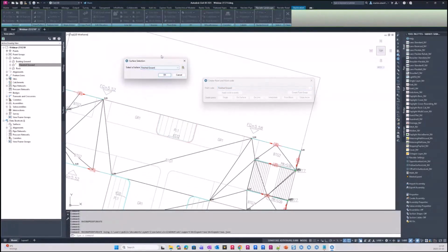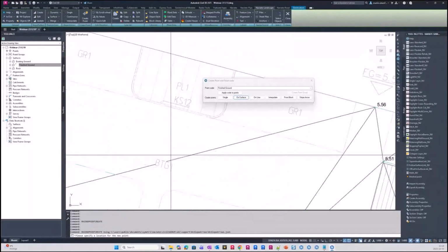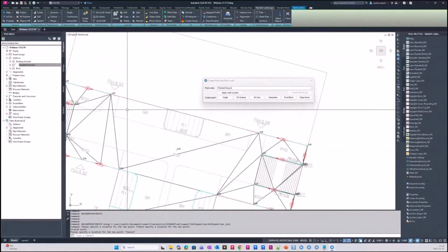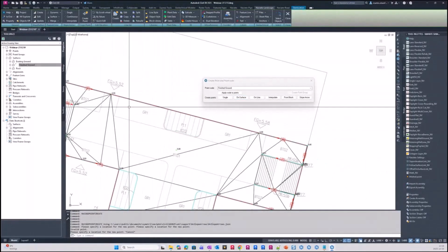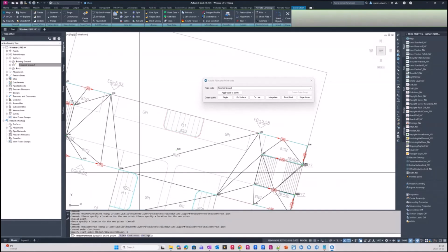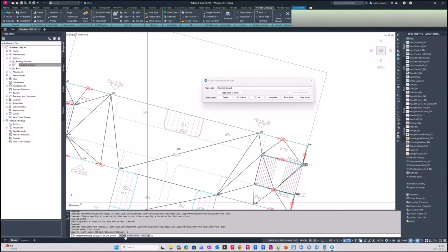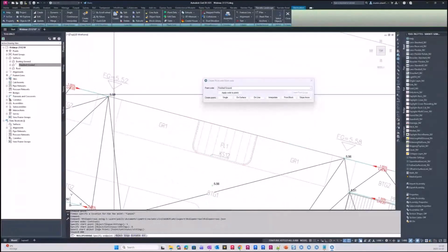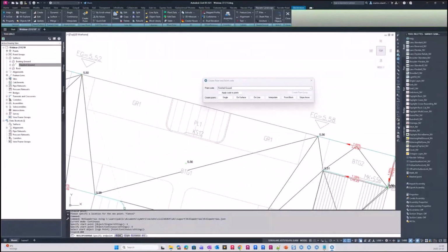I choose to get the height from the finished ground again. Hit OK here and place my point over there. And I want to check the elevation or do some edits here and see what slope I get from different other points. I can just use this single again, and then I choose object instead of point. And then I can just pick this point, and I pick object again and pick this point. And then I get those 2 points connected with the slope arrows.